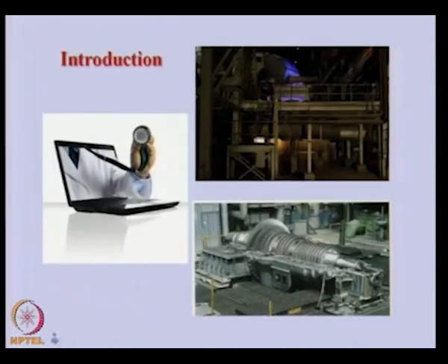So, coming to the condition monitoring in industry, obviously in industry we need to capture various kinds of signals, either a vibration signal or temperature, pressure, noise. Various kinds of signals we need to capture, and then those signals we need to store in a computer, analyze them and try to correlate various kinds of faults which may appear in this kind of machinery, and then we can have some kind of database.